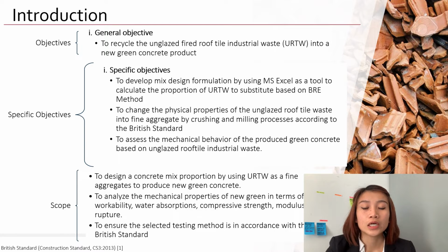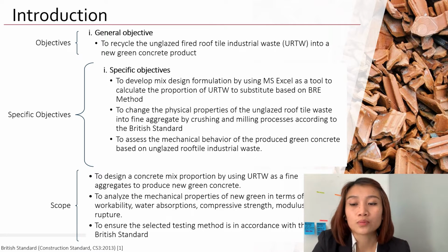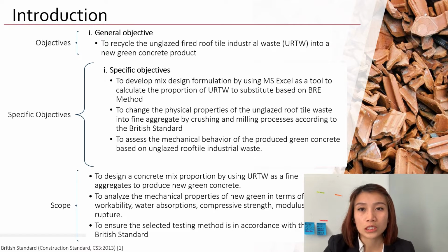The second is to change the physical properties of the unglazed roof tile waste into fine aggregate by a few processes, first crushing and second the milling process, and all of this procedure is based on British standard. So the third objective of the project is investigating the mechanical behavior of the produced green concrete at 28 days that is based on unglazed roof tile waste, and then comparing it with conventional concrete.